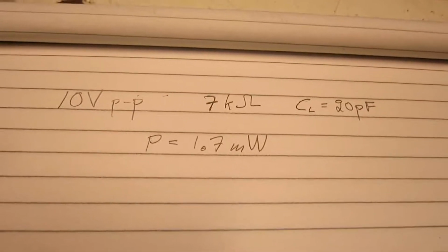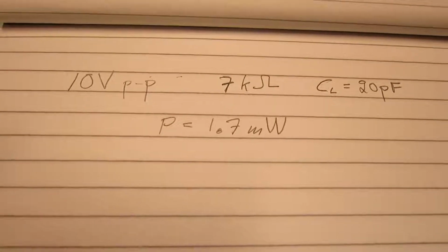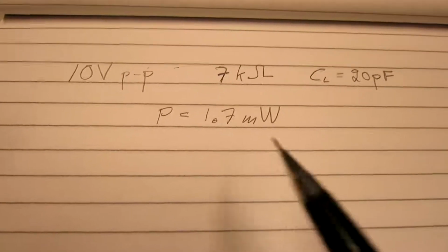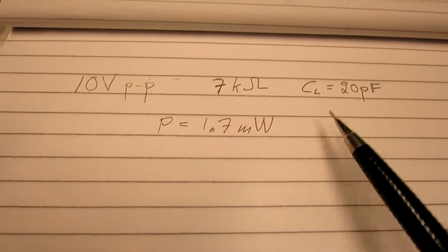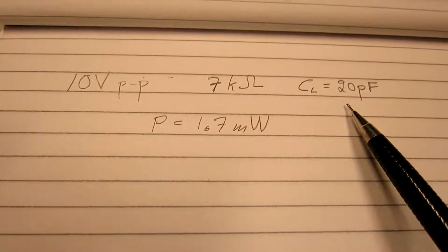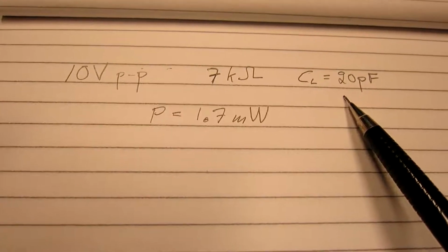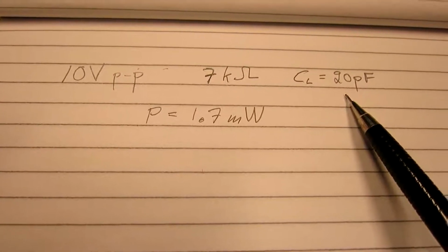So I can estimate this to a power level of 1.7 milliwatts. The total load is that 10 pF loading plus the two 4.7 pF coupling capacitors.